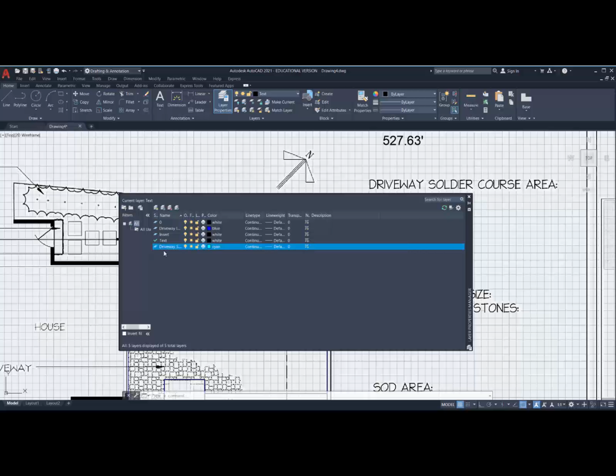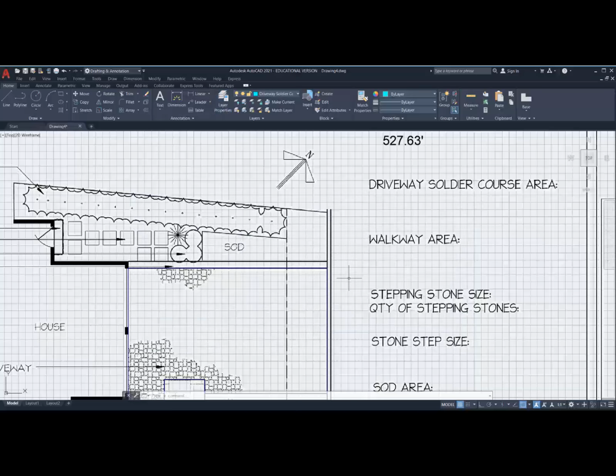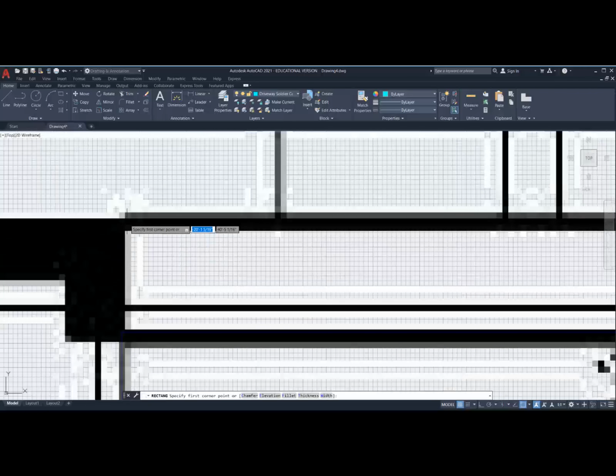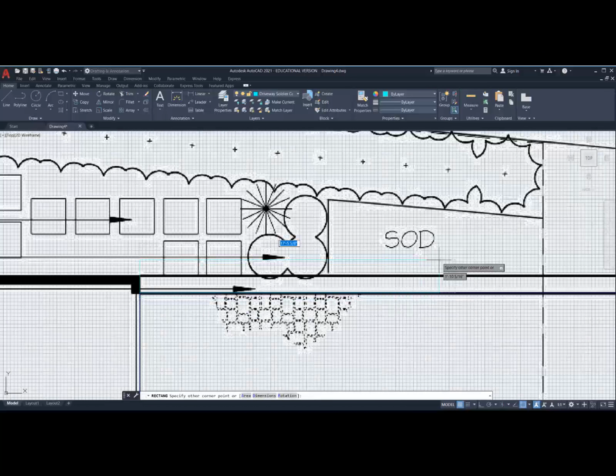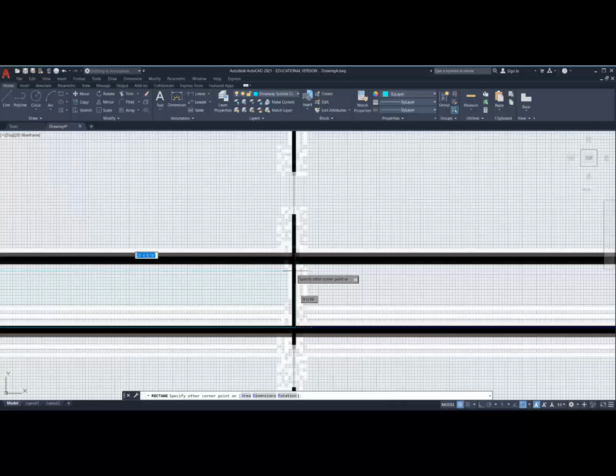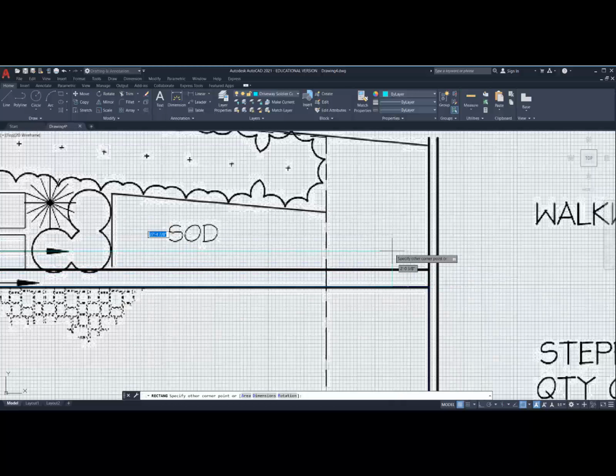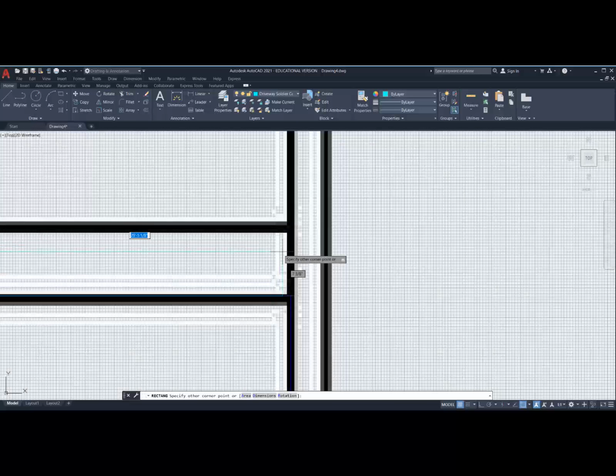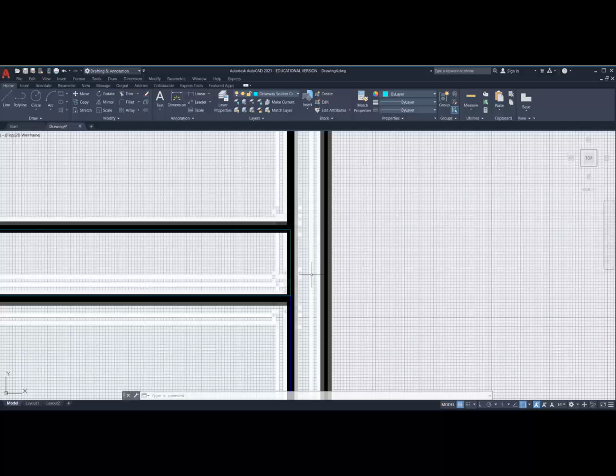So why is that important? So here's the big difference with this. I'll make this current. This is a rectangle. Easy enough. I'm going to click on the rectangle tool. I'm going to pick part of the driveway that doesn't have a polyline right now. Or what I can do now is actually snap to a location that I already have. And by doing that way, I have some accuracy that I otherwise wouldn't, because it guarantees that I'm not going to overlap. See where I have it here? So I can go straight up here and click to this location.